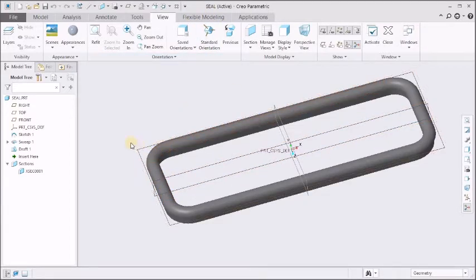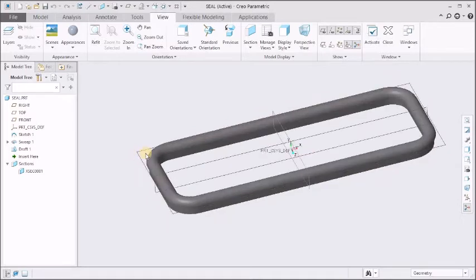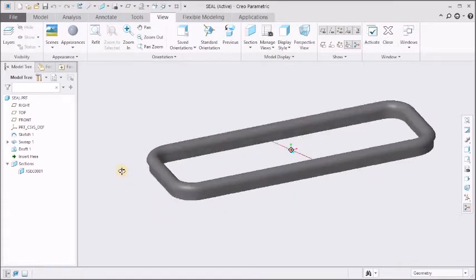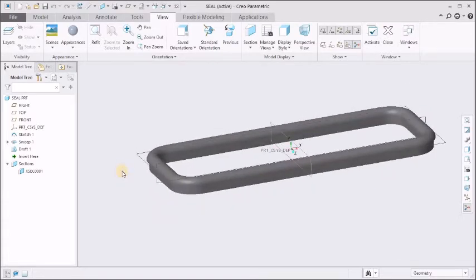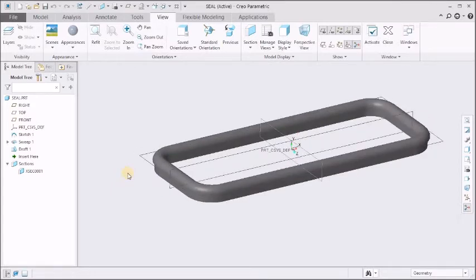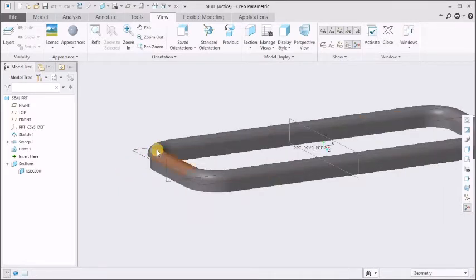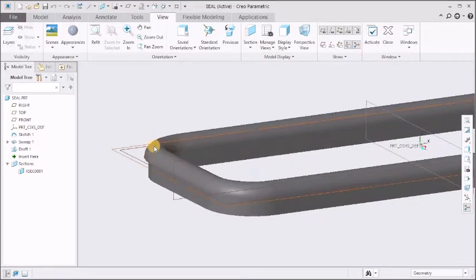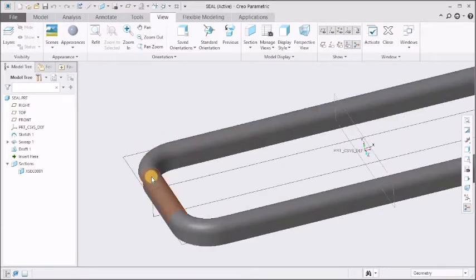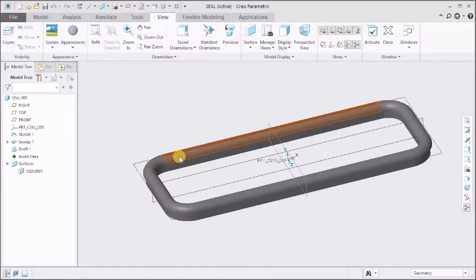that we have created. I know the shrinkage value for NBR is 2.4%, I use it and I'm getting good results. Of course, the fundamentals of calculating shrinkage are very complex, and a lot of experience is needed when we add shrinkage. But for the sake of understanding, let us see how I do it. I just add the shrinkage by scaling